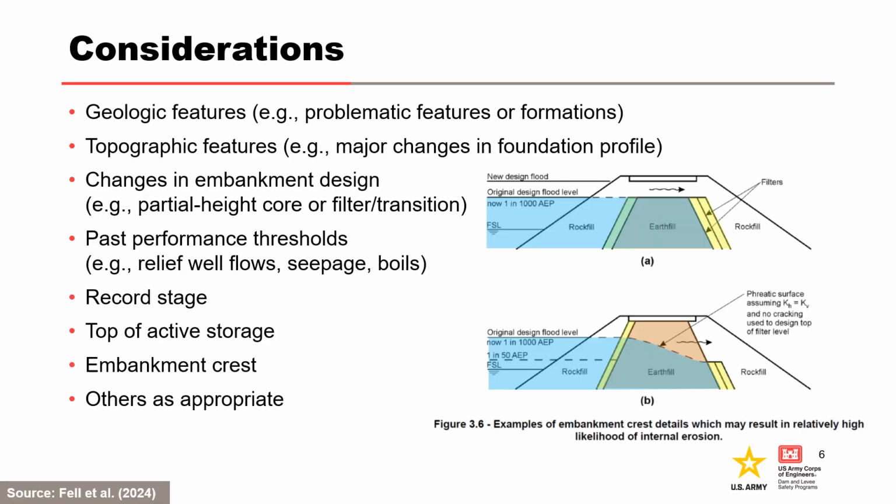Several factors to consider when selecting loading partitions are shown on this slide. Always evaluate performance up to the embankment crest, even if the probable maximum flood is at a lower elevation. Other potential inflection points include major changes in the foundation profile, changes in the embankment cross-section, past performance thresholds, record stage, top of active storage, etc.